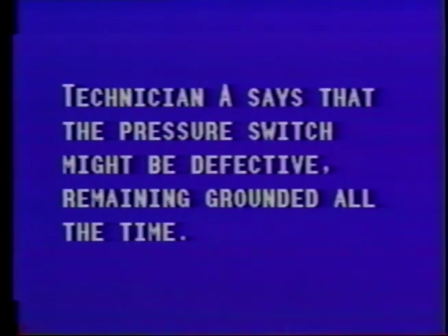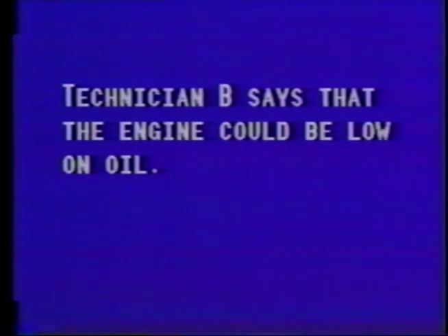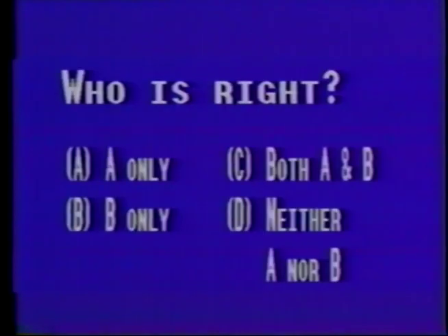The engine oil warning light remains on all the time the engine's running. Technician A says that the pressure switch might be defective, remaining grounded all the time. Technician B says that the engine could be low on oil. Who's right? A only, B only, C, both A and B, D, neither A nor B.